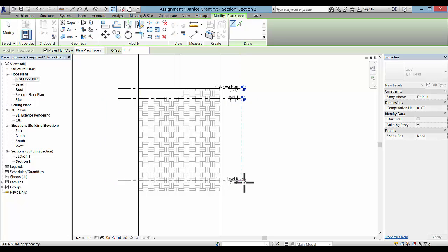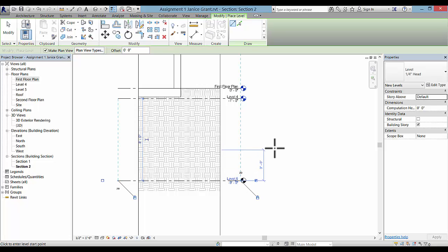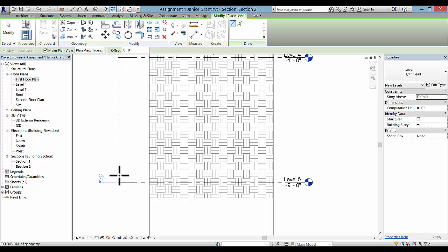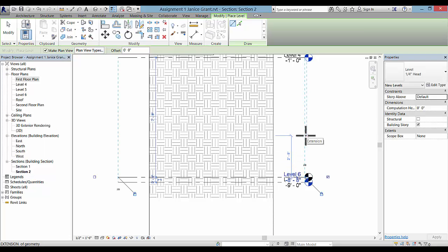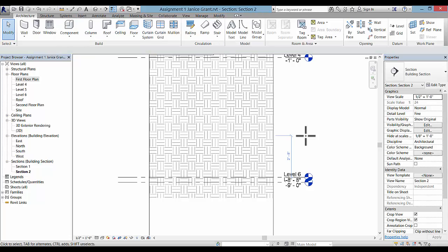So we'll go 8 foot here more. And one more that we should create is the basement floor that we can work off of. And we can make that one 4 inches here as another level. And it depends on your wall section. It could be different for commercial drawing.